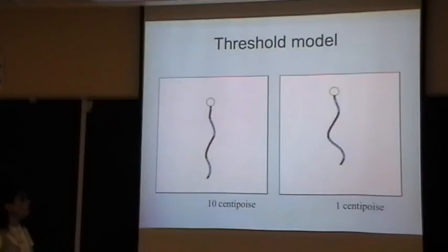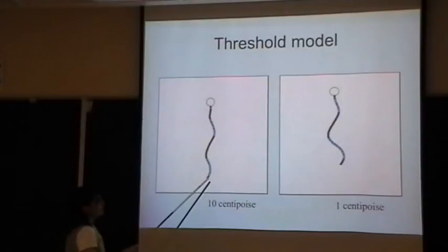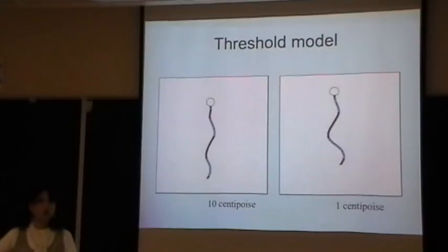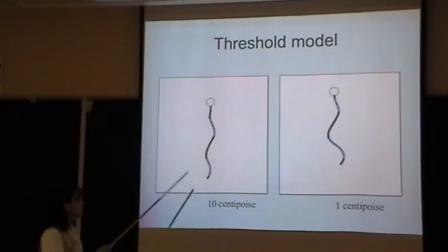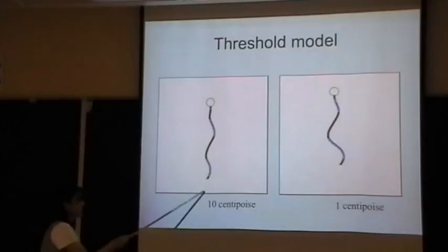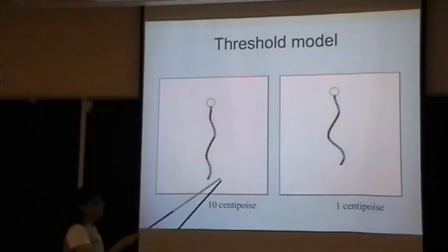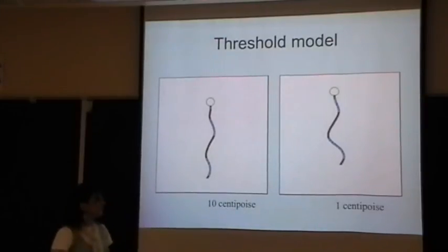So what we're doing is we're comparing these. We're in the process of writing up a paper now where we're comparing these dynamics within the Newtonian case to experiments. And what's done in experiments, yes, there are viscosity changes. This was done in the 60s, and when you change the viscosity, it is shown that the wavelengths actually decrease. So when the viscosity increases, the amplitude decreases and the wavelengths decrease, which qualitatively we're getting here.